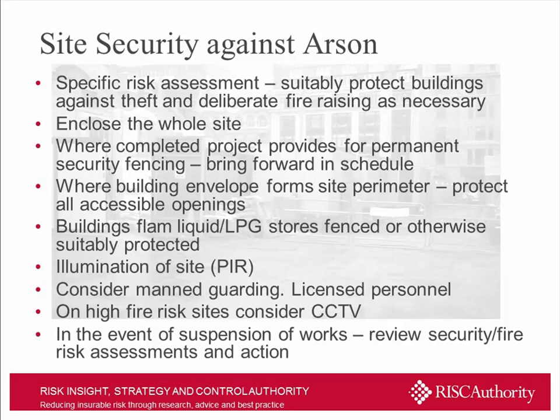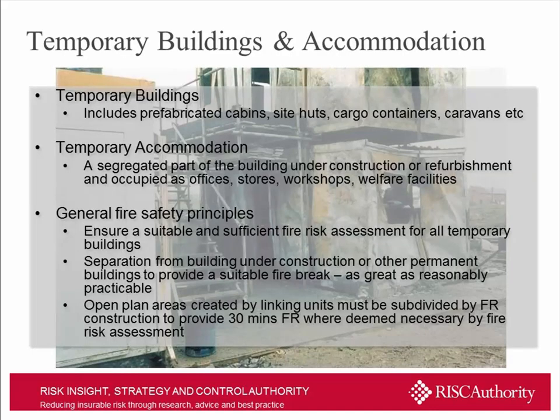And of course, in addition to that, perimeter protection, making sure that if you have anything that's particularly flammable by way of gases or HFO, flammable liquids, highly flammable liquids, that they're kept suitably secure. Temporary buildings and accommodation, we're introducing combustible materials onto a site. Very often there's a need to put any temporary accommodation into the building under construction, and the code makes some specific requirements with regard to their use and where they should be placed.